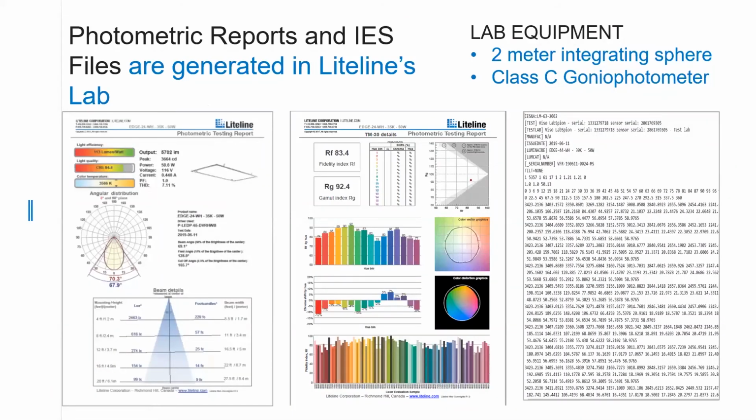Color temperature, by the way, can also provide a slight edge in efficacy for LED light sources. The higher the color temperature, generally, the more lumens you will produce from the exact same source than from that source with a lower color temperature, such as 3000 Kelvin.